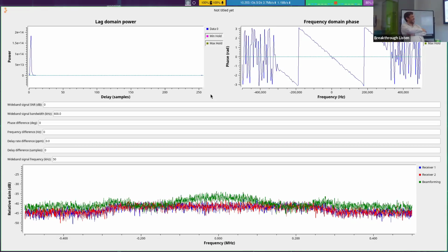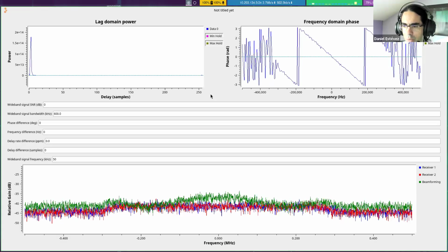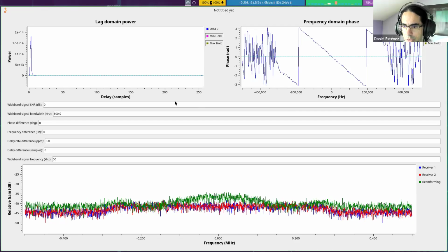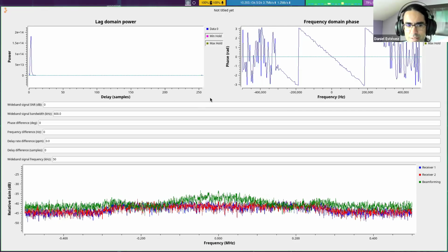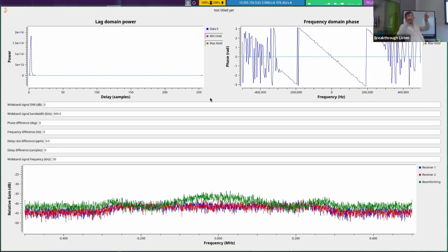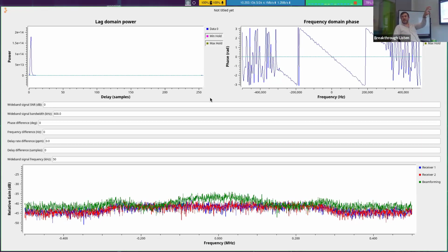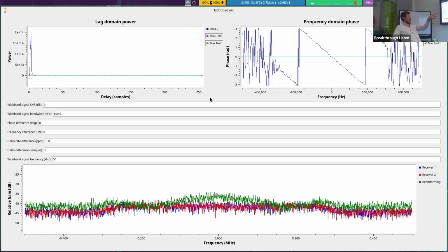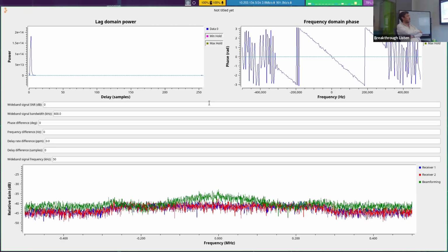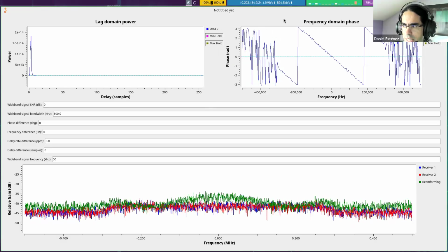Yeah, I bet we will also see one of these plots for the ATA where we see all the antennas and we see the phase differences with respect to a reference antenna. And of course, the point is with the ATA, where you've got multiple antennas, you're pairing up each antenna with a bunch of other antennas. And so then you can often see which antenna is the one that's causing the problem because it appears in a common set of pairs with the other ones. Okay, so that's the end of this demo.